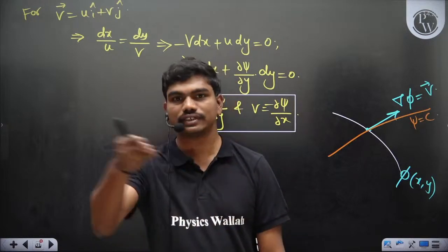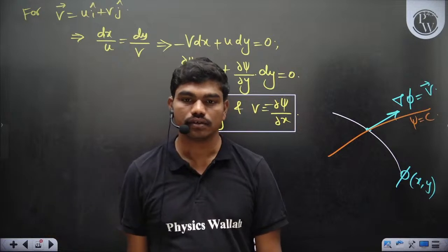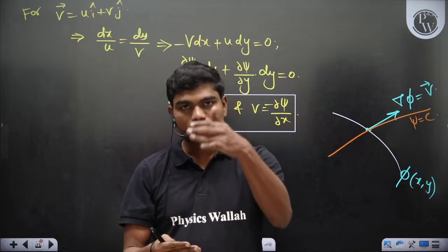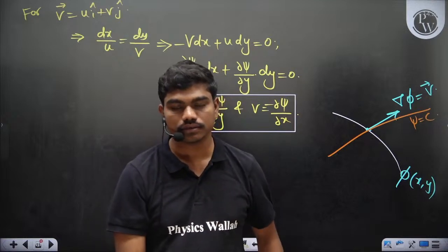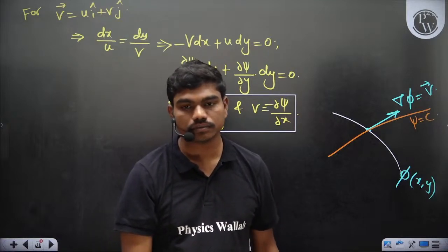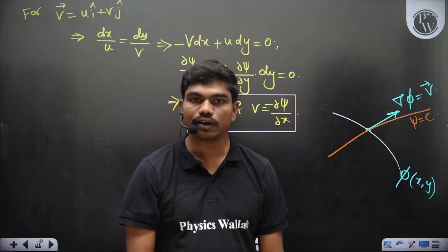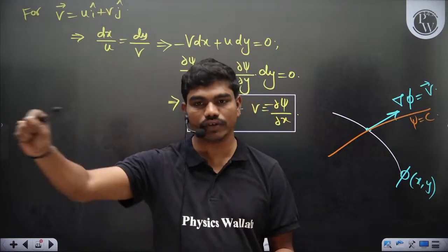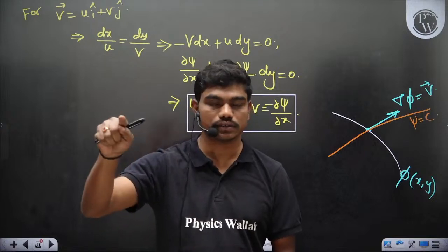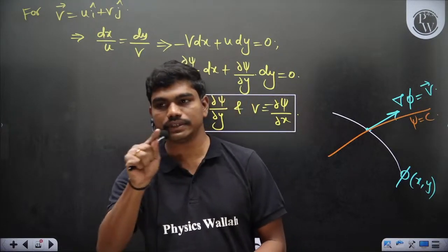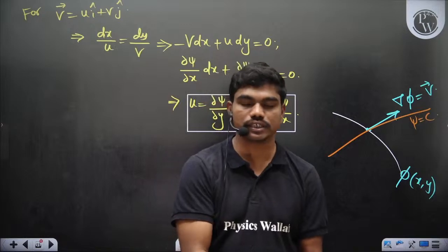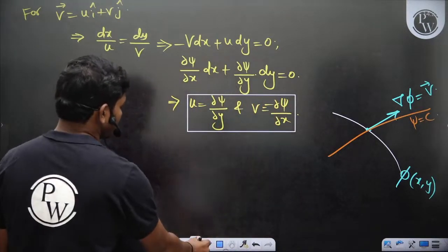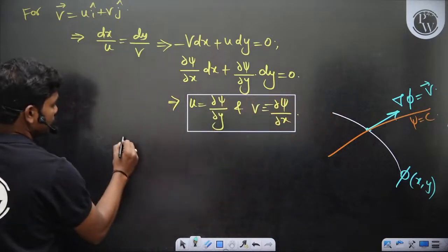Even in compressible flows, you have streamlines, correct? Particles can float and you can have a streamline definitely. At every point you have velocity, so you can always generate a curve for which the tangent is the velocity. Did you all get this? Even if you have a compressible regime, you can see the gas particles moving, and at every point you can have the velocity. If you know the tangent, you can keep generating the curve. That's what your Runge-Kutta fourth order methods, all these numerical schemes, do.